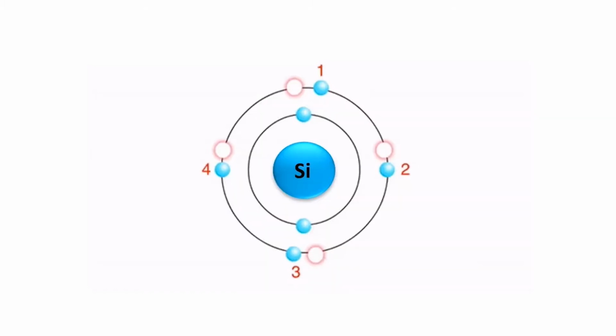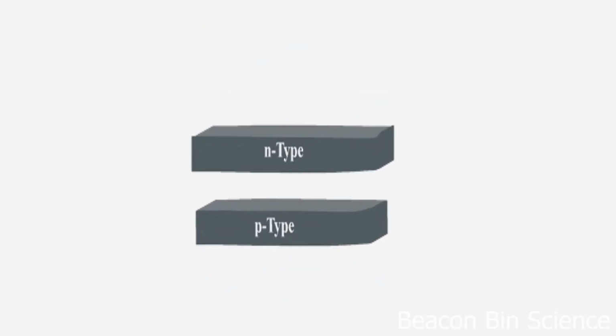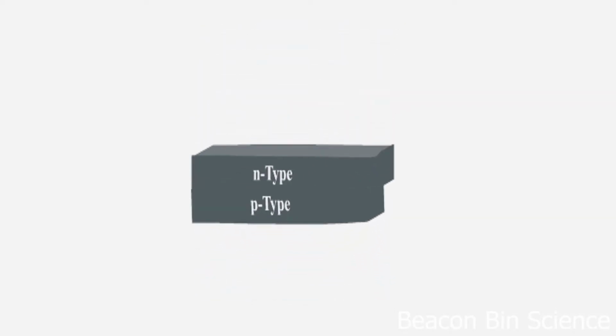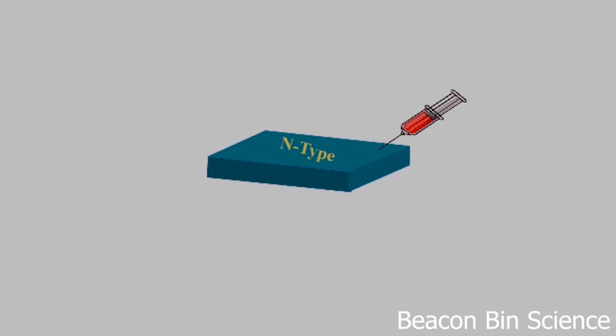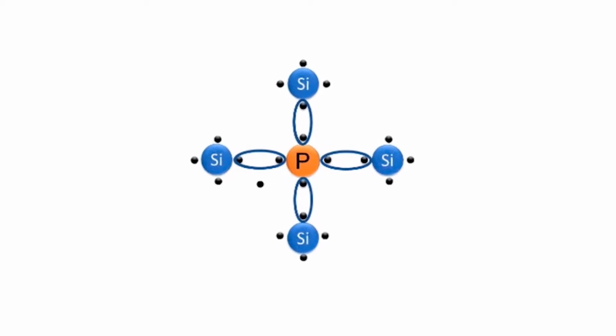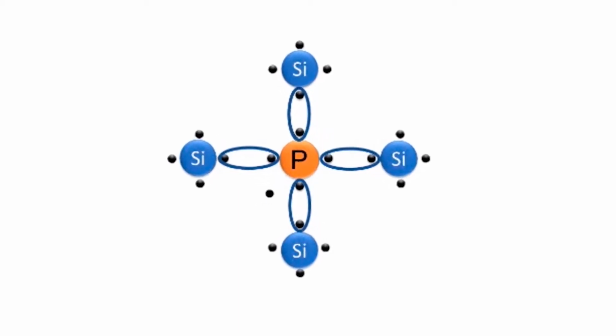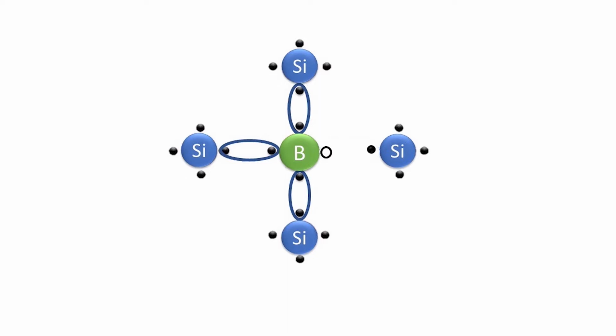Silicon atoms have 4 valencies, which means one atom of silicon bonds with 4 other silicon atoms. Each solar panel cell is made up of 2 layers of semiconducting silicon. One layer has a positive charge and the other a negative charge. The charges are added to each layer by adding other materials to the silicon. For example, pentavalent phosphorus is commonly added to silicon, which results in an excess of electrons and makes it an n-type semiconductor, while boron addition creates electron deficiency and makes it a p-type semiconductor.